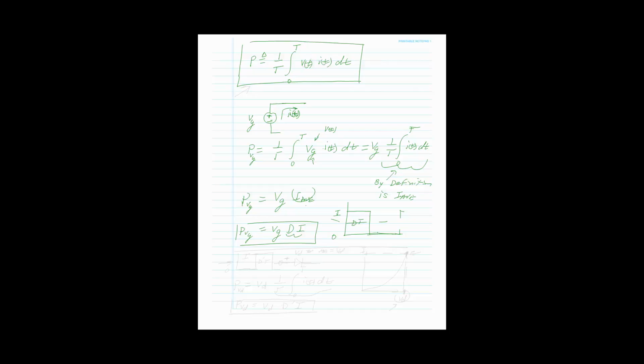What if it's not sourcing, but supplying through a diode D? At some point that diode is biased here, so we can consider the diode current and some fixed diode drop. We can imagine that as a voltage source drop, which is VD. Later we'll add in the series resistance, the resistance of the diode. So now what's the power dissipated in the diode?